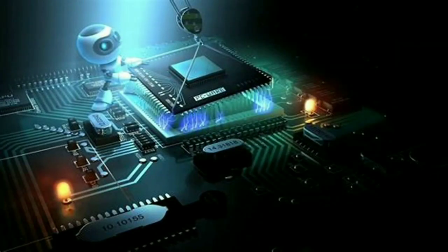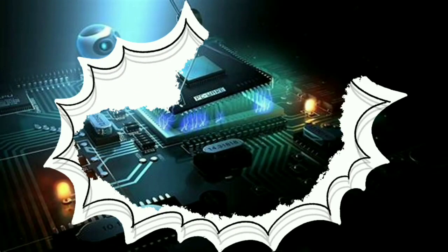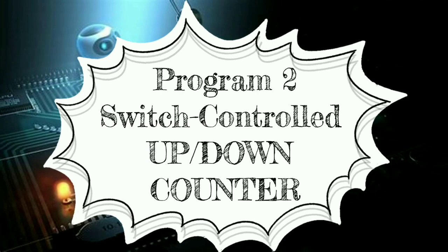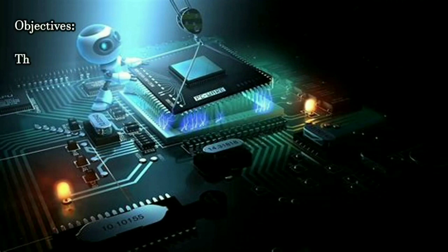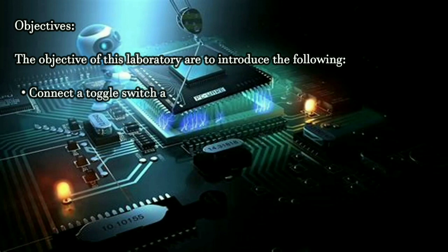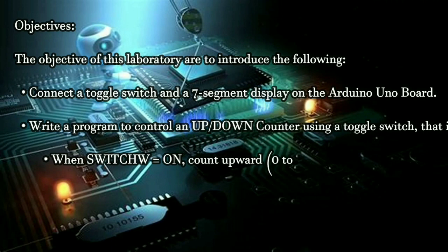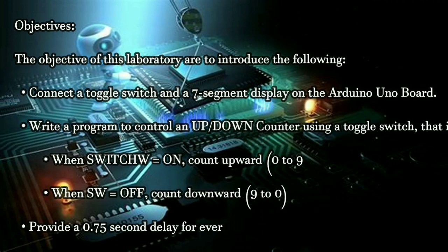Now let's proceed to our program 2, the switch controlled up or down counter. Our objectives for this program are the following. Connect a toggle switch and a 7-segment display to the Arduino Uno board. Write a program to control an up-down counter using a toggle switch, that is, when the switch is on, the counter counts upward 0 to 9, otherwise it should count downward 9 to 0. Provide a 0.75-second delay for every count interval. Run the program and verify that it works properly.